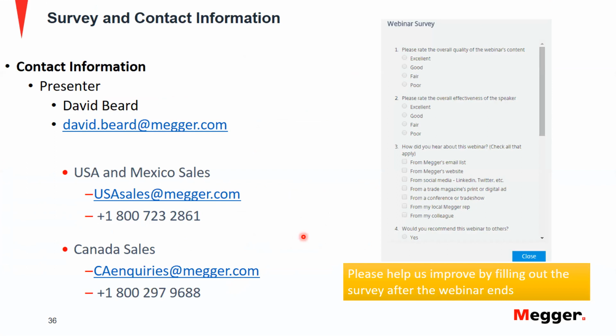So our first question is going to be directed to Sugosh. Instantaneous is never really instantaneous. Can we calculate the magnitude of this instantaneous time? Yes, it is possible to determine this instantaneous time. The easiest way to do this is by running a timing test on the instantaneous function. So you could have 2 stages of test set, wherein you can create a pre-fault state and then switch on to a fault state wherein it actually injects the instantaneous value, and then the relay trips for the instantaneous time.